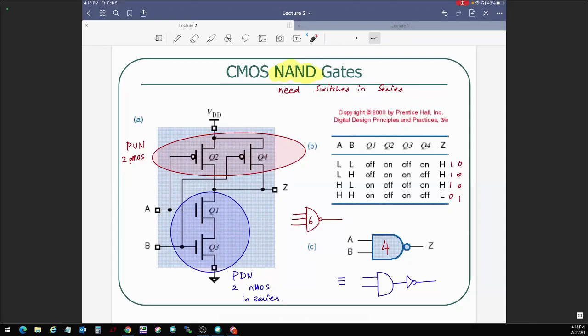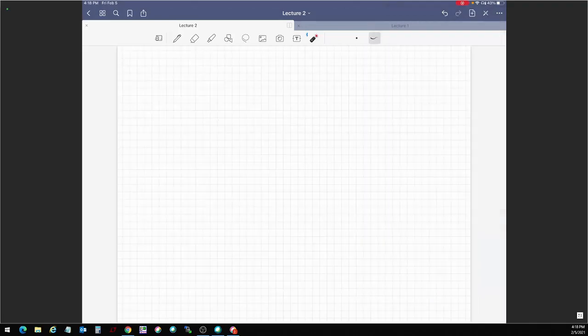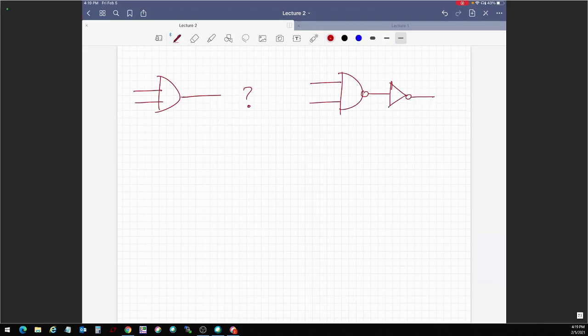Beautiful. Now let's talk about something where we are going to try to connect a few points here. So how do I get AND then? How do I get this? Not NAND. Yes, brilliant. So you first design a 2-input NAND, then you cascade a NOT gate in front of it so that these two things cancel out. The two bubbles cancel out. Double negation cancels out, right? So when you have a bubble and you have another bubble, the bubbles cancel out. 0 becomes a 1, 1 becomes a 0. Double bubble. Yes.